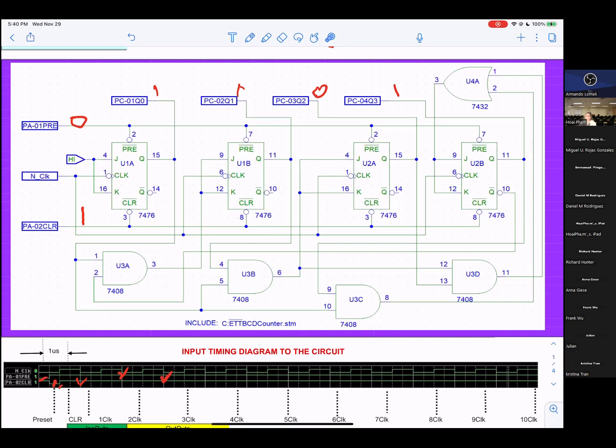Is U3 relevant? I mean, if U3. No, we don't have U3 right now. We're talking about you fail on U2 pin 5, right? You take power, you take ground, you take input here, you take input here, everything okay. That's why you're asking for a new IC. And you get the IC and rerun it, you still get 0. Would it be a problem with PC 3?